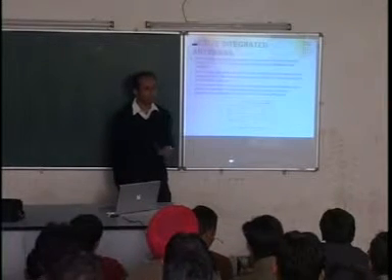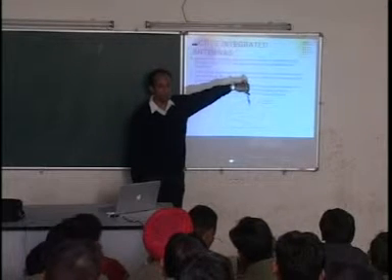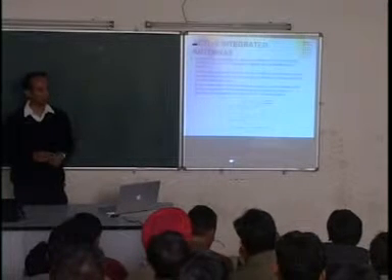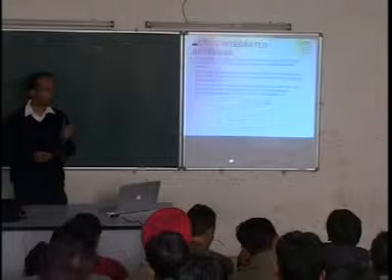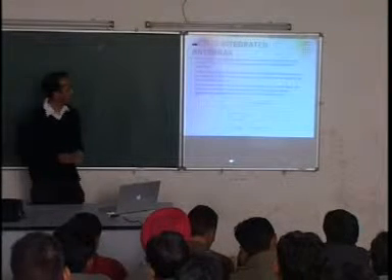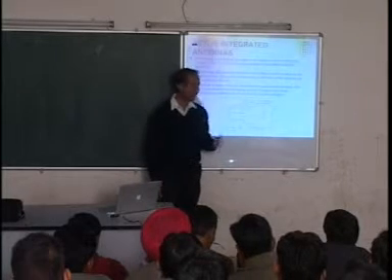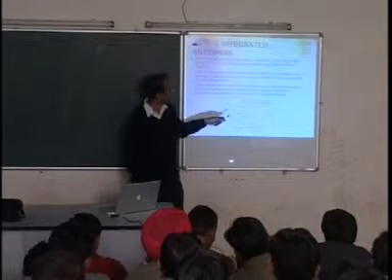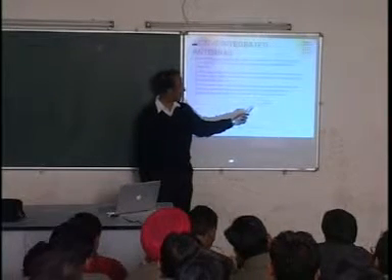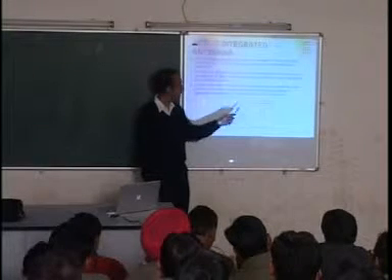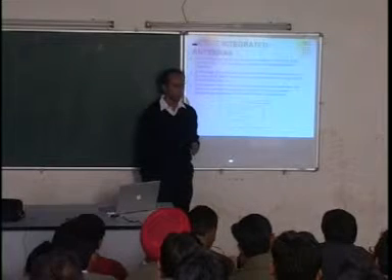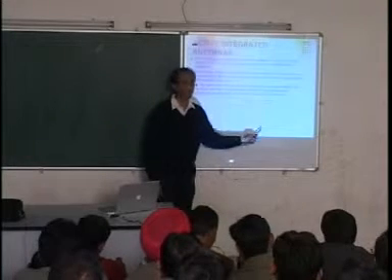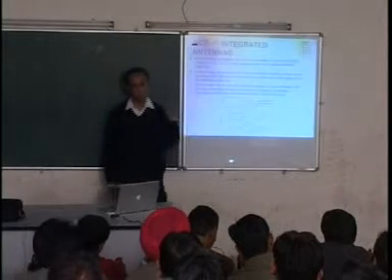What does this do? This is a category of antenna which are called narrow band or almost single frequency. This particular antenna has a single frequency of operation, a very narrow band antenna. At that center frequency and throughout that small band, what does this antenna do? Input signal, half comes out, half is radiated out. Outside that narrow band, what does it do? Input signal, all goes back, reflected. That's how this particular antenna behaves.